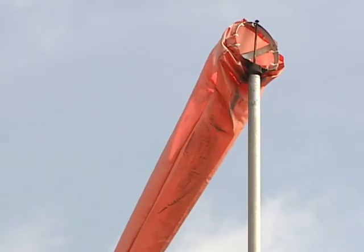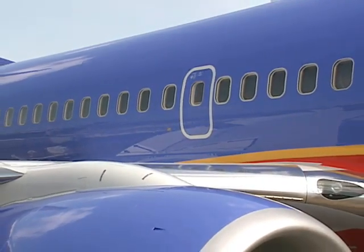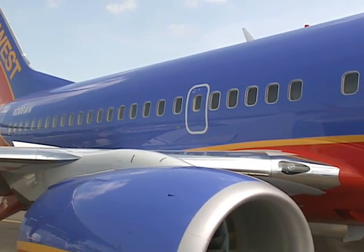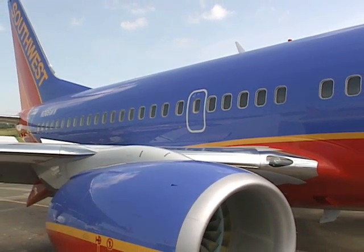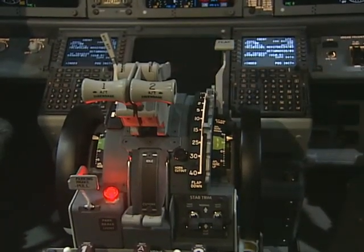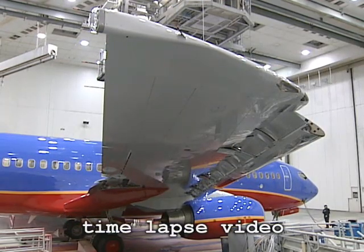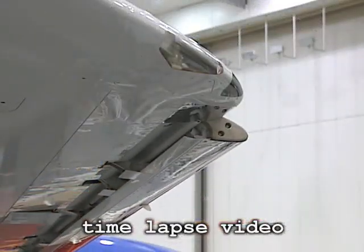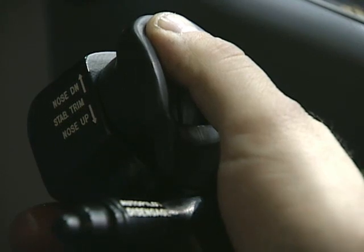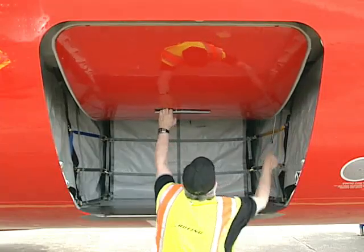The building should be large enough so you can completely close the doors with the airplane and tool vehicle inside. You should control the ventilation system so that there is no air movement. In addition, the floor should be level. Note that Boeing has no technical objection to weighing airplanes outside as long as wind conditions at the time the weights are recorded are within the limits considered acceptable to your regulatory authority.